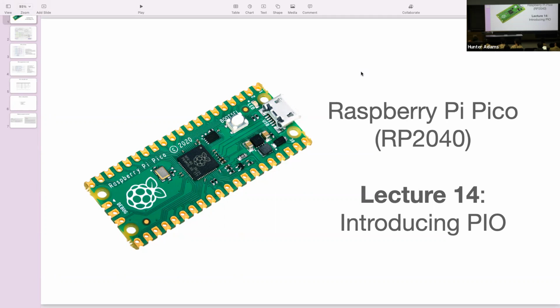Another common bug is to remember that the other parameters associated with this algorithm, things like the turn factor and the centering factor, are given to you in the write-up in a decimal value. Just remember that you need to translate that to a fixed point value. Suppose you're initializing the turn factor, right? And you say, okay, fix 15 turn factor equals, and you want to give it the initial value.